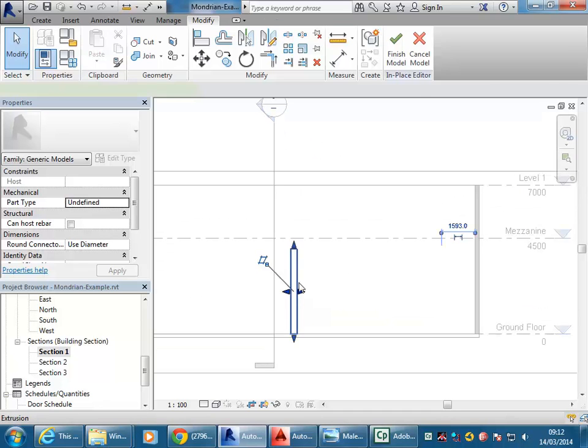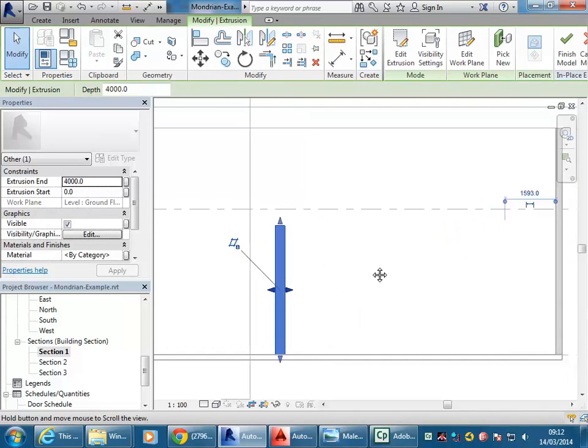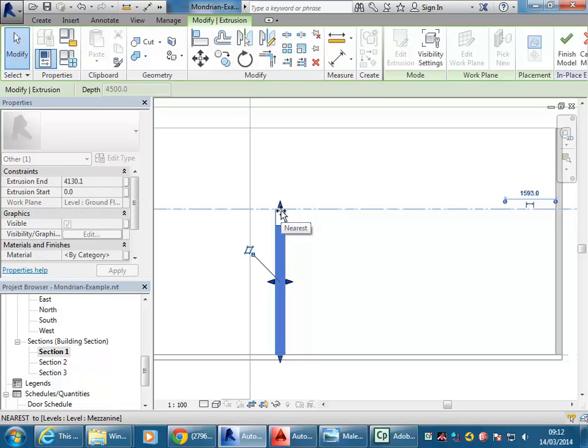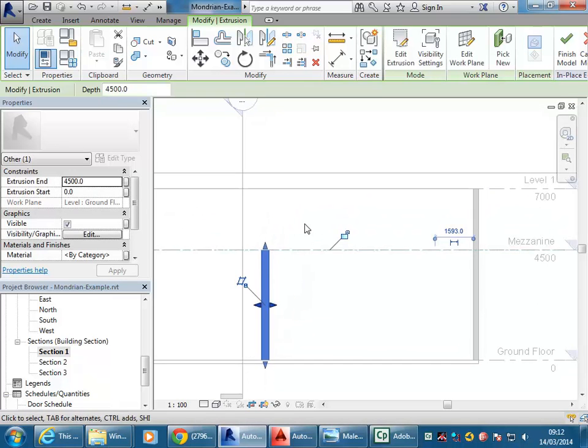And so if I select just one of them there, you can see the arrow for up and down. And I'm going to drag that arrow at the top onto my level, that mezzanine level I made. Okay, and so then you should get a padlock symbol, which you can lock, and so then the height is set by the level. So all of the columns fit the height? Yeah, they would exactly, because I've made all of them as one extrusion. Okay. So they're all one object. If you want them to have different heights, just make extra extrusions. Exactly, don't copy them within the extrusion.